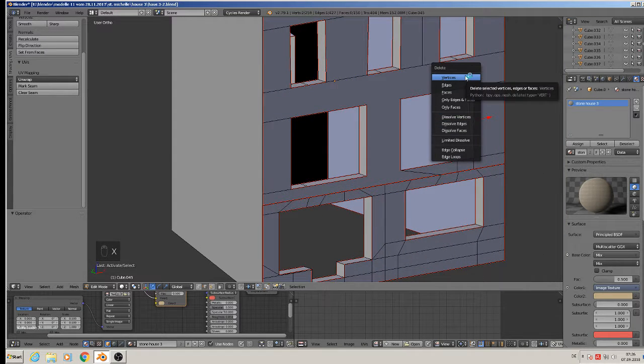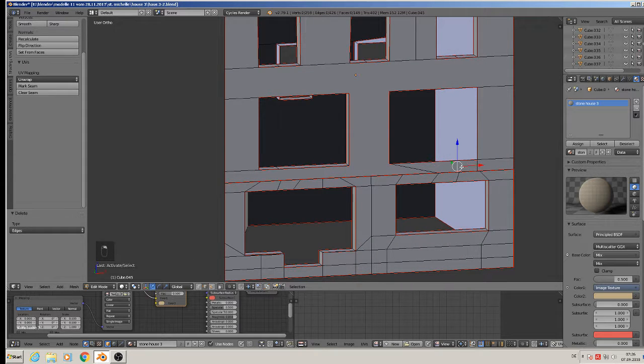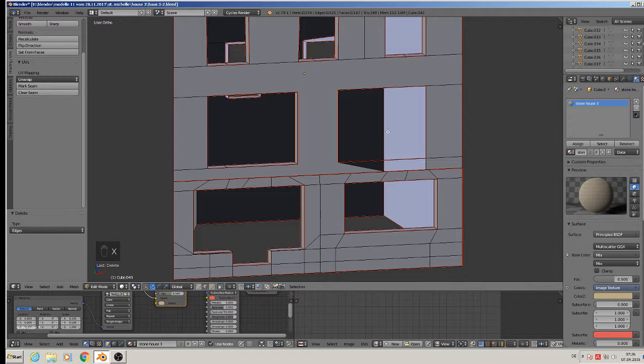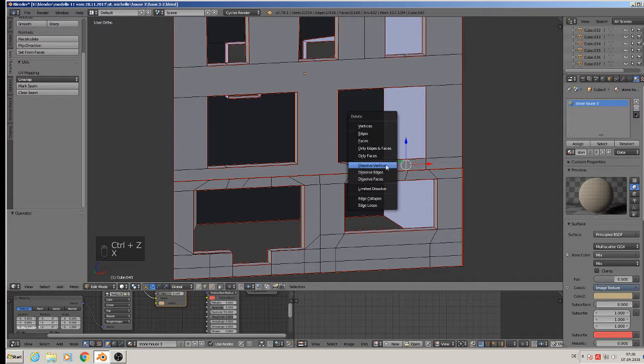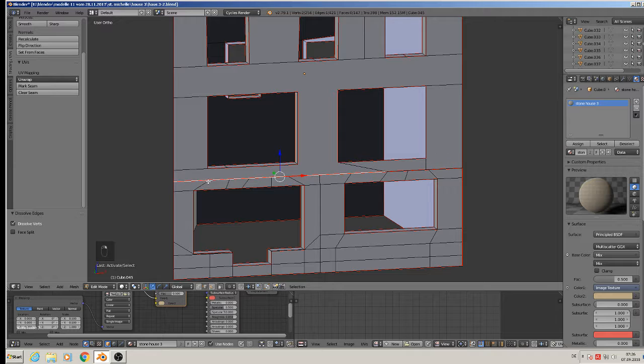So better is when you really made the cuts by hand, and then model the house. Don't model the house and then use a boolean. That is the wrong way to do such. But I know what you say, why do you do it then? Because it is faster. I like fast modeling, and the rest is not important for me.